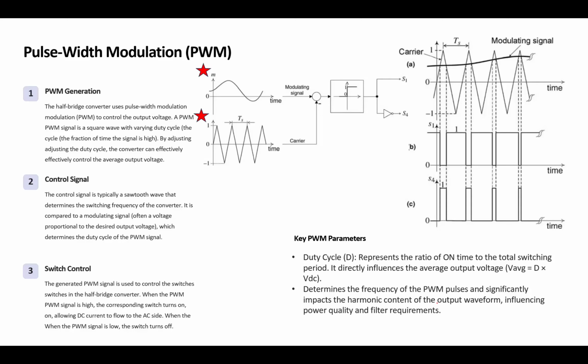Now, the objective that you want might be control of the load. Simply, like if the load increases, you have to increase the power, meaning you have to increase the duty ratio. Simple. Remember, M was the gain. If the point is to reduce distortion, then we need a different technique to change the pulse width dynamically to reduce the harmonics or eliminate some of them. We are going to talk about them.